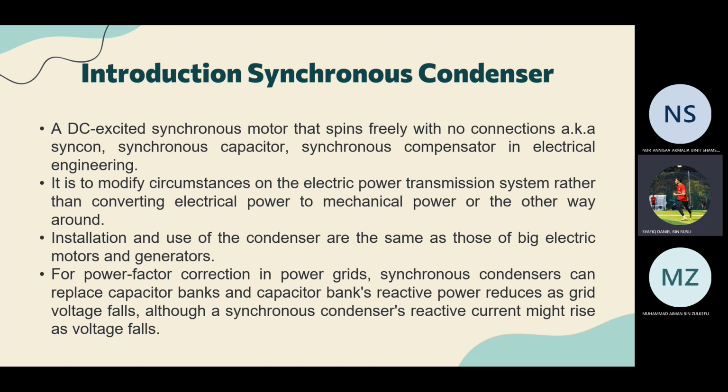A synchronous condenser is a DC excited synchronous motor that spins freely with no connection, also known as a synchronous capacitor or synchronous compensator in electrical engineering. It is used to modify circumstances on the electric power transmission system rather than converting electrical power to mechanical power or the other way around.